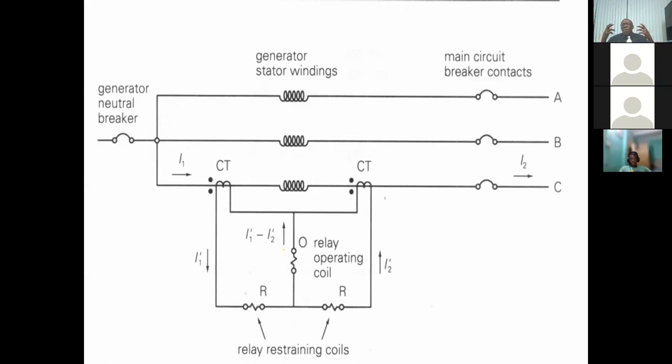A fault does not necessarily have to be on the transformer; it can be a fault outside of the transformer. The transformer cannot decide that it will not allow the fault current to pass through. Of course, if the current is going to exceed the maximum operating current of the transformer, then the overcurrent protection for the transformer will operate, because you can pass more current than the windings can handle. We agree on that? Yes, sir. Good.